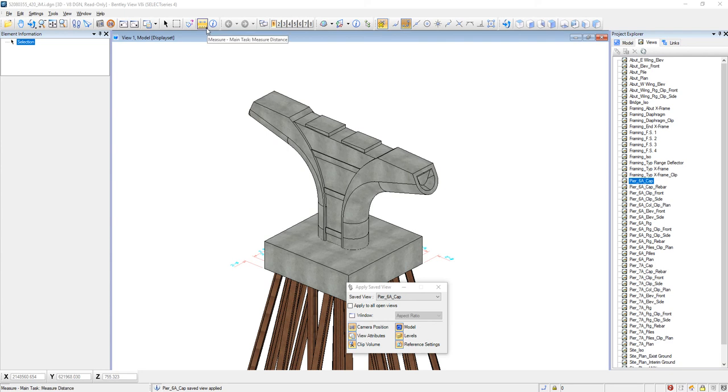and you can see there's actually a little arrow on the bottom right. That's pretty standard for Bentley View. If you see that arrow, it typically means that if you hold down your left mouse button, there's other tools within that toolbox. And usually you can open those up as their own separate toolbox. In this case I didn't. Again, you can dock that if you want. Actually, let's just do that. So let's open that up as a toolbox. And you can see there's different functions.